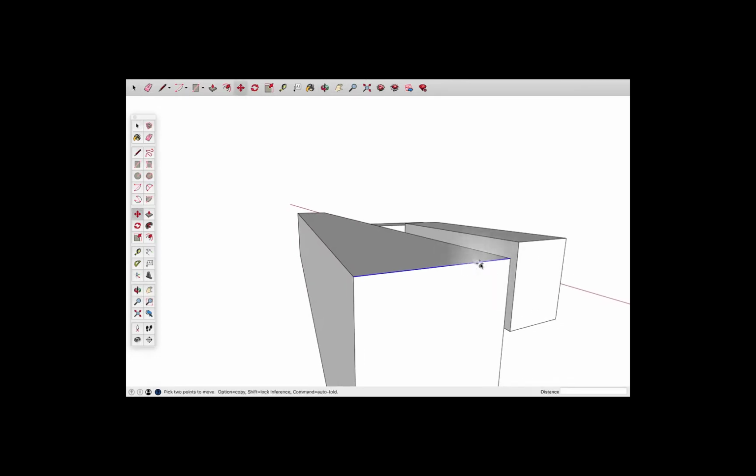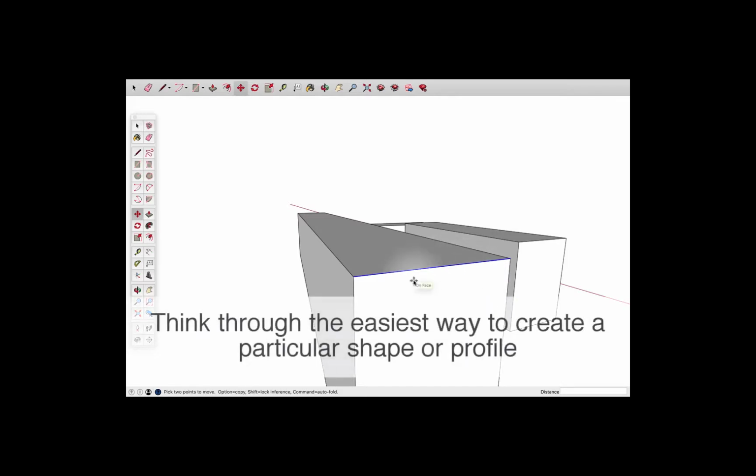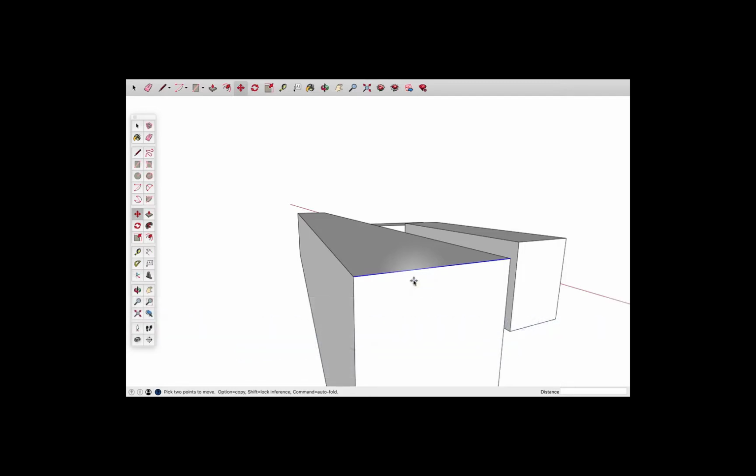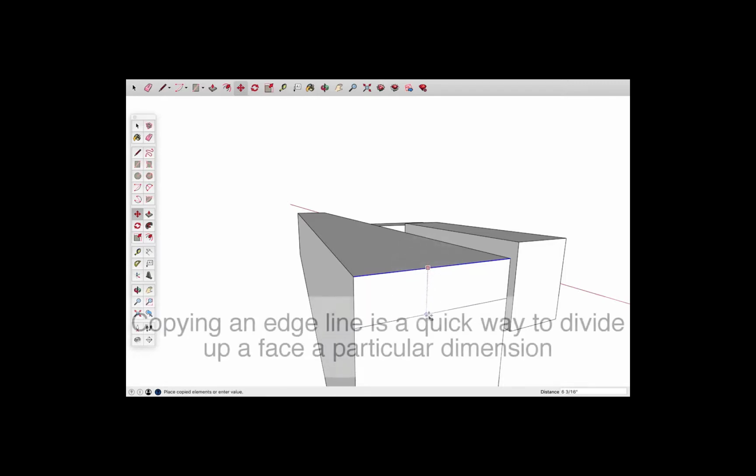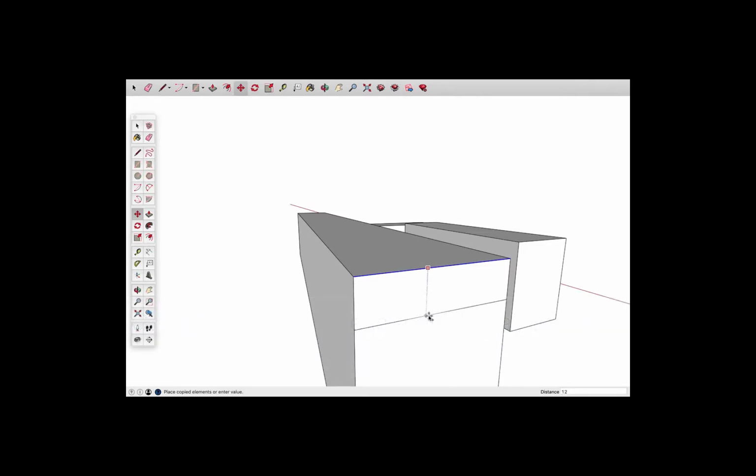I'm going to just draw the profile along the edge here and push-pull it down. And that way I can really think about what my countertop is going to look like. So first of all, I'm going to select this line. I'll use the Move command and tap Alt or Control on a PC. And I'll copy it down, and I'm going to go with a 30-inch countertop, but my service counter part is up at 42, so I want to move this down 12. And again, I'm just trying to demonstrate possible techniques for how you could do this.